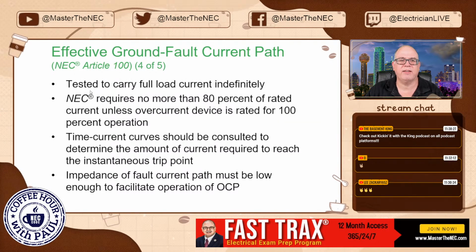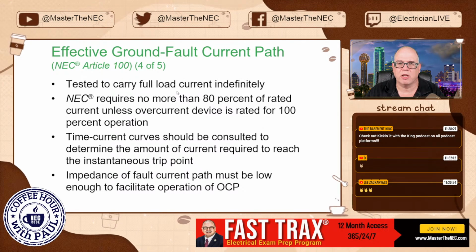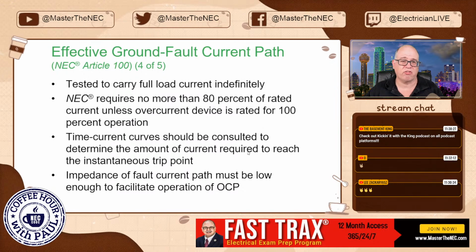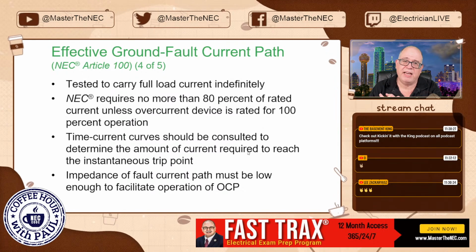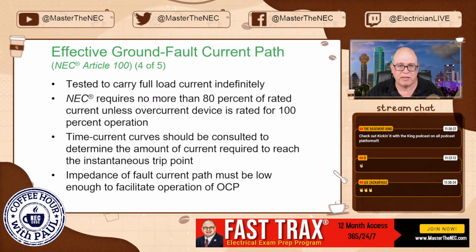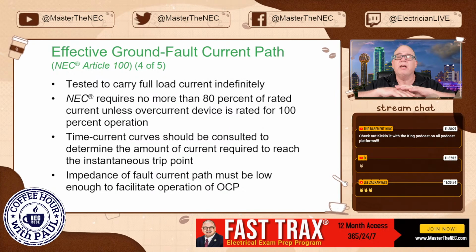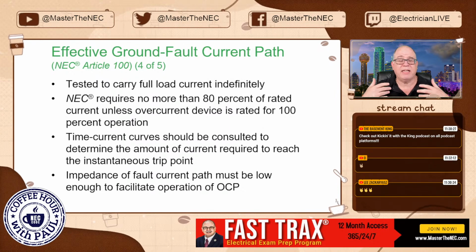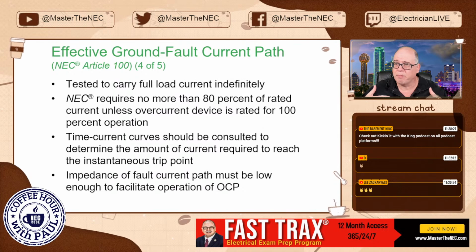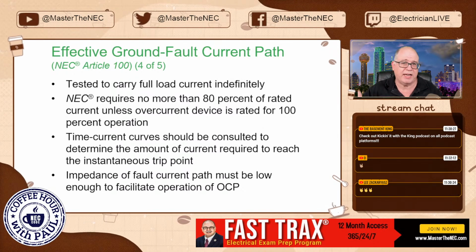All right, tested, so effective ground fault current path, tested to carry full load current indefinitely. Anytime you have a path and it's all constructed using listed components or fittings that are listed for the type of wiring method you're using, then it has all been tested. It's all been considered, sized per the NEC and, of course, any applicable standards.